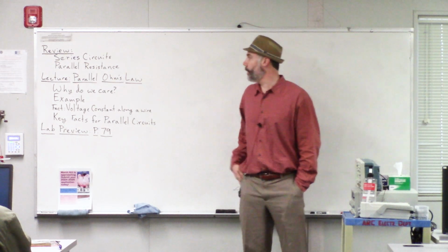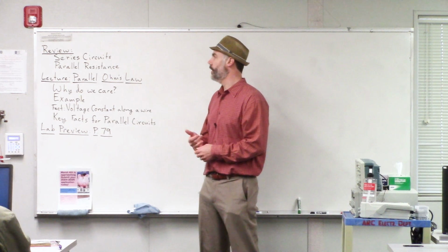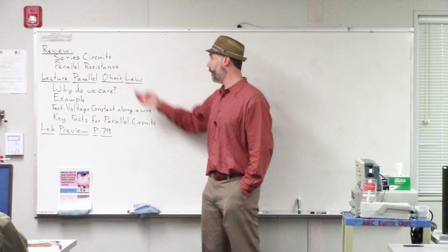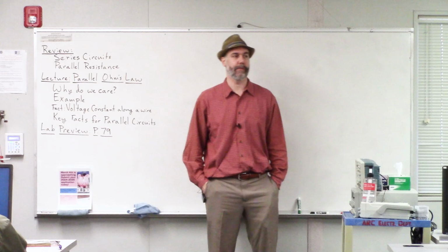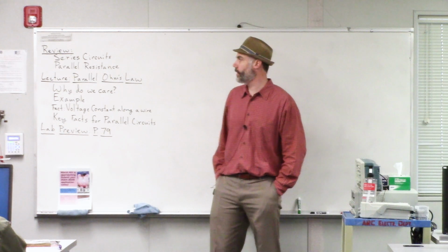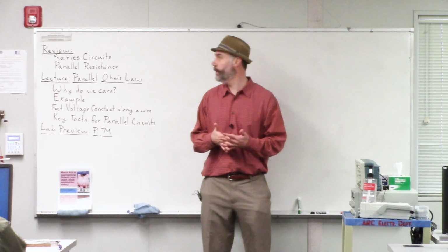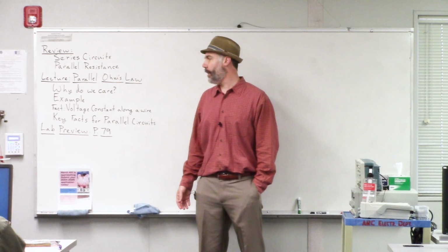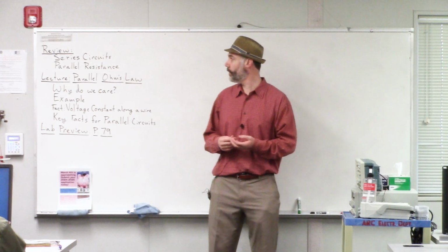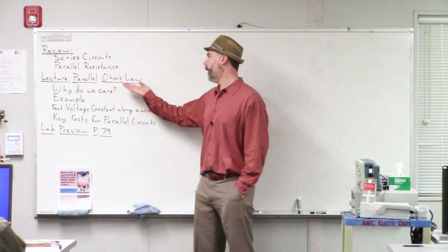So today we're going to start with a review of series circuits. We talked about series circuits two lectures ago, so we're just going to go over those briefly, and then we'll talk about parallel resistance. We talked about that last time, and we said that this was a little bit counterintuitive. We said series circuits kind of made sense because when you got more resistors, you ended up with more resistance. Kind of stands to reason. But with parallel circuits, it was the opposite. When you got more resistors in parallel, you ended up with less overall resistance. So we'll review that. And then we'll go on to the main topic for today, which is parallel circuits with